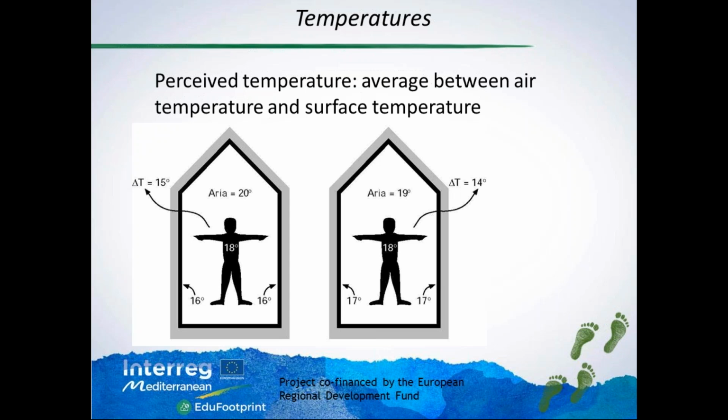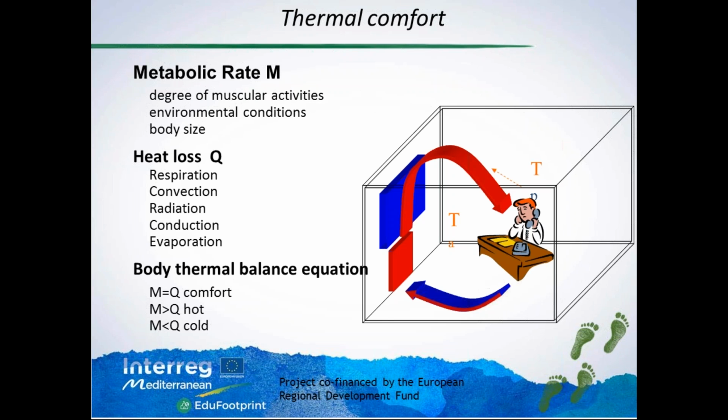If we have a well-insulated envelope, the temperature will be higher. The temperature of the air is what we have to provide through a heating system. This has an impact on our running cost, on the operating of the building. So this is one reason why we have to take a real look at the status of the outer envelope.